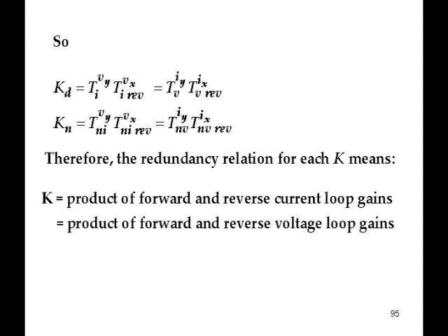Now, if there is no reverse loop gain of either voltage or current, the product term disappears. But this is how you incorporate that non-ideality. And this is exact. You hope the result is going to be small. And maybe it is and maybe it isn't, but in either case you'll know what it really is.